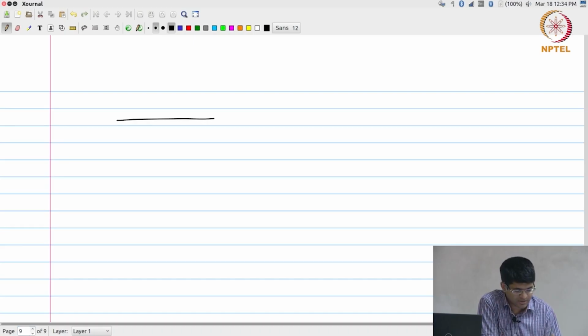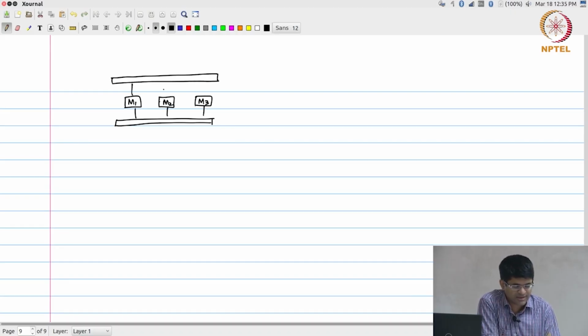Okay. So what I am saying is, I have this simple system over here which has M1, M2, M3. Okay. What if I also put another bus out here and just connect all three to that also? This is probably a bad example because there are after all only 3 devices, so let me just add one more over here. Now what I could have is, I can think of a situation where, let us say, M1 is talking to M2 and at the same time M3 is talking to M4. Both communications can go on at the same time, because they are happening on different buses.